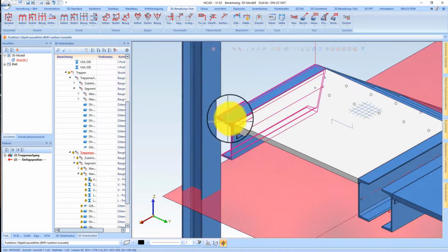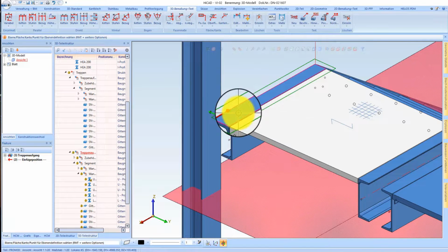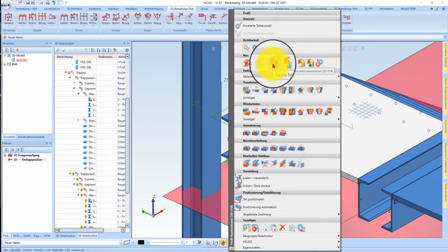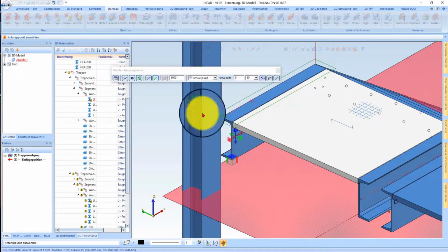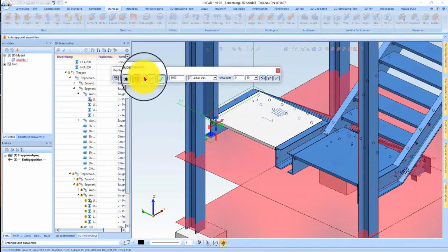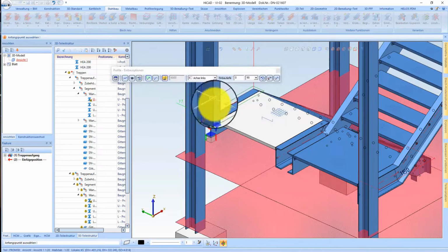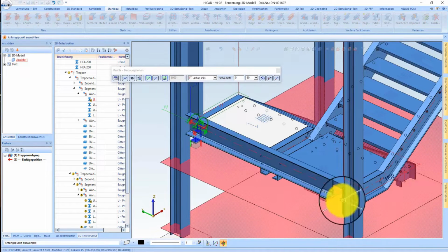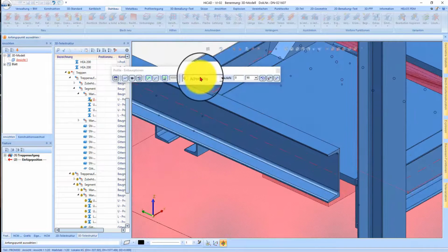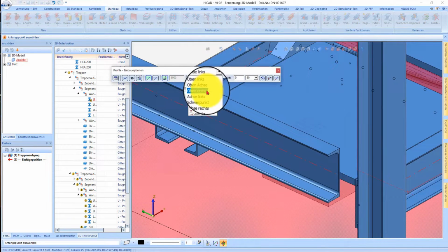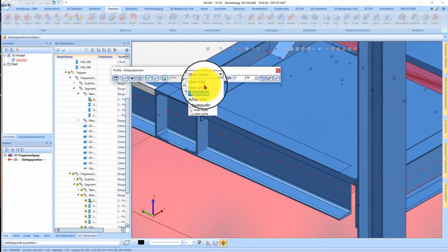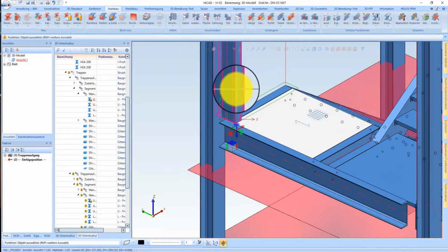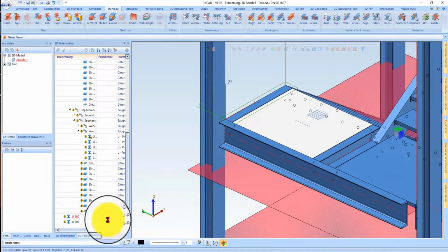That means I can, for example, place my plane here and say I want to adopt this profile, and it should go from here. So wait a moment, that's obviously the wrong function. I need to go through the sketcher from here to here. I'm just roughly fitting it in. The position is basically already correct. I can now say top left, like this, and have, for example, immediately integrated my profile here.